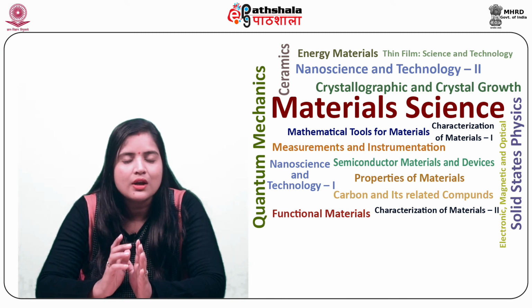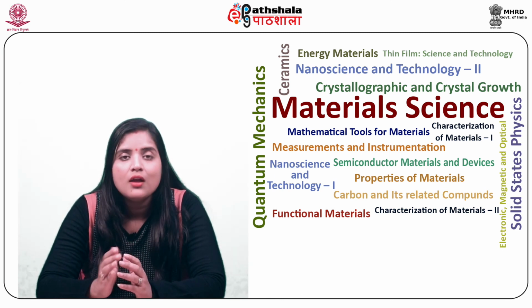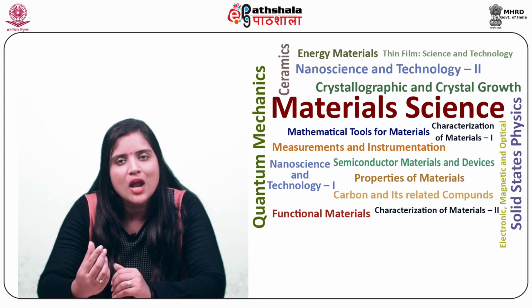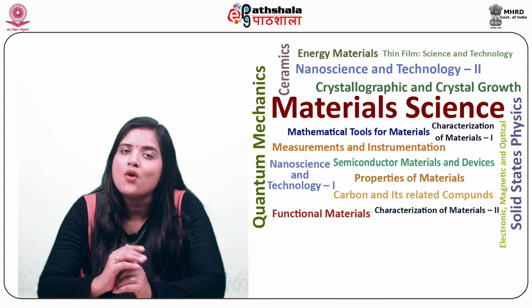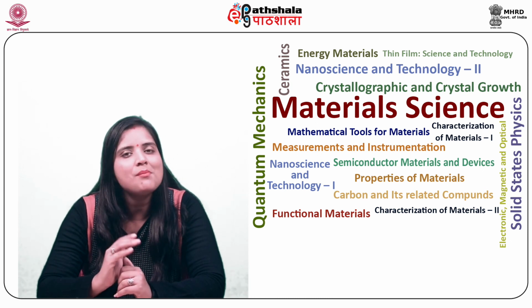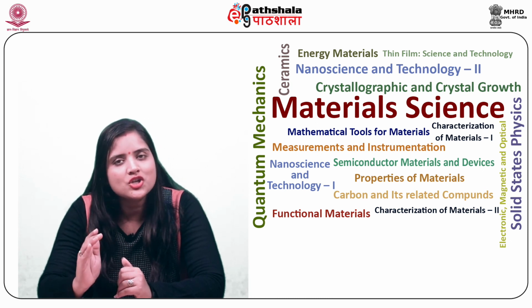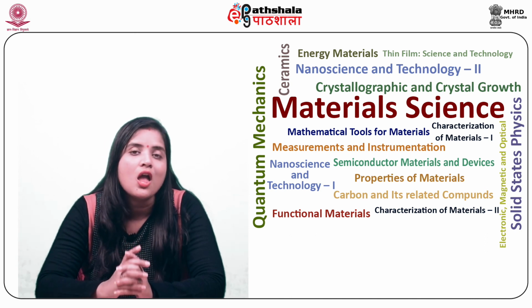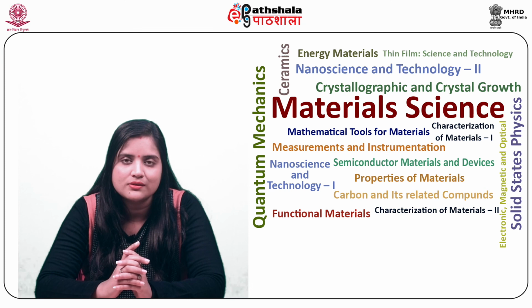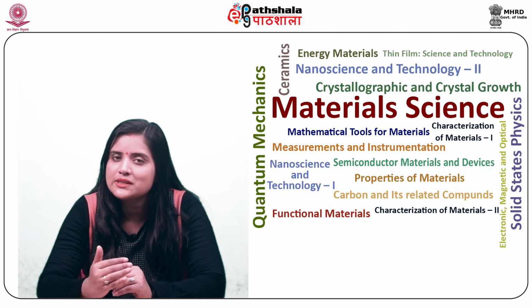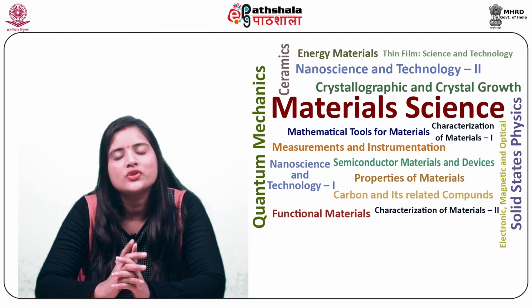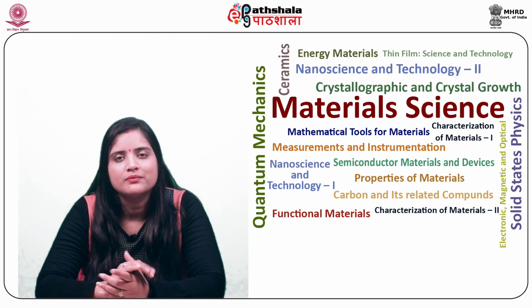Let's now understand accumulation. The negative gate source bias forms a p-channel at the surface of N region, which is similar to the case of N-channel, although it is having opposite charge and voltage polarities. The increased hole density results in increased capacitance, which is observed in figure.